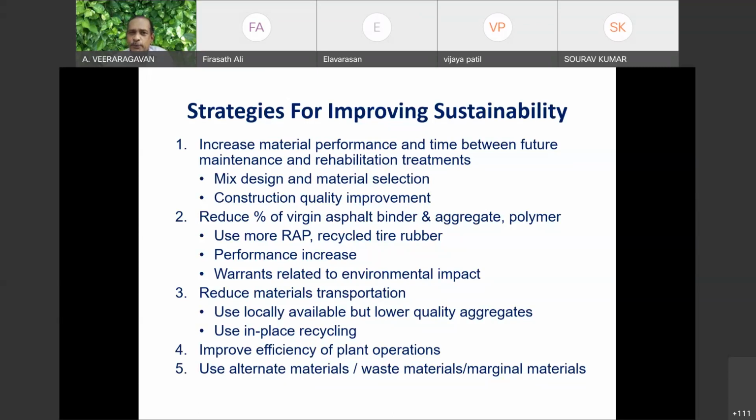Maybe the liquid limit is more, plasticity index more, free swell index is more, proctor density is low, OMC is high, CBR is low. So once you test the soil, I know what is the lacking property. For example, the soil has got too much of fines. That means percentage passing through 30 micron is more than 35%. Will the soil perform better? Definitely not, because fines are more. Is it suitable? No. Can I improve the performance? Yes. Can I do stabilization?